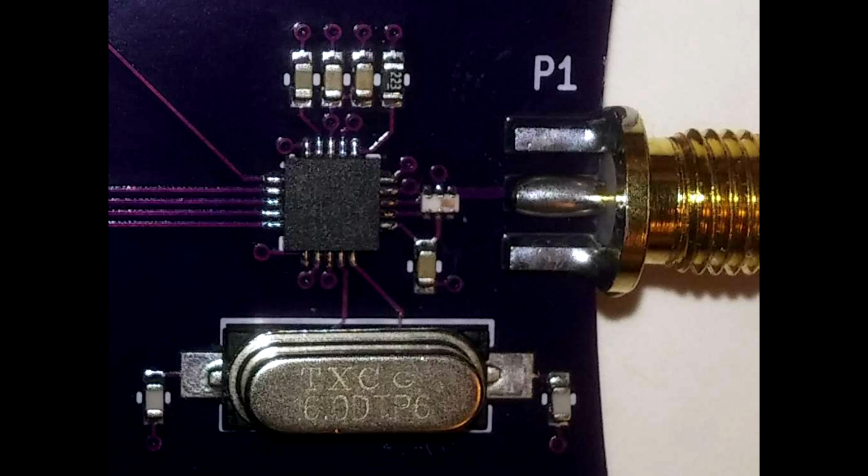And this entire circuit here, almost all of it, is taken directly from the manufacturer's recommendations, and there isn't much to it. There's this crystal oscillator, a couple of load caps, a few decoupling capacitors, and this one bias resistor. That's a very common thing you see in these types of designs. And then look over here, between the antenna connector and the IC, is this thing right here.